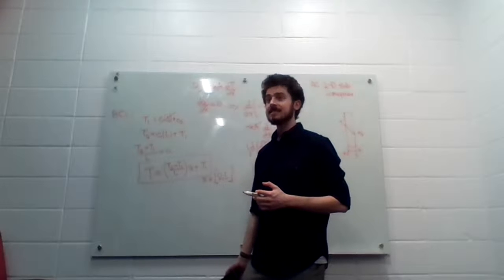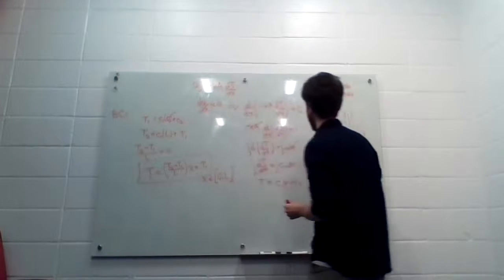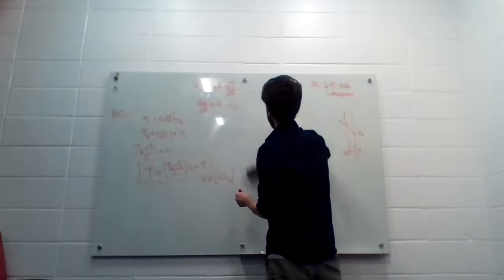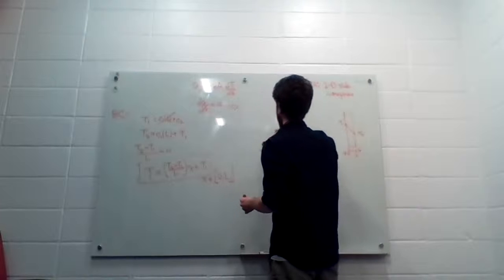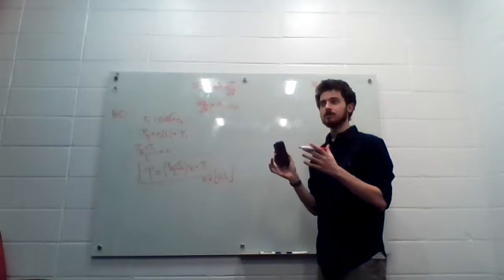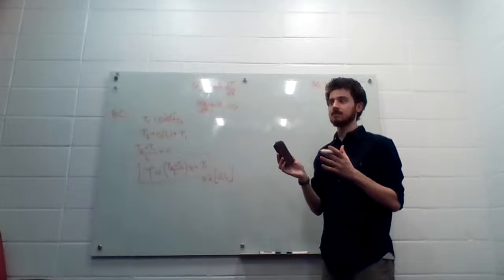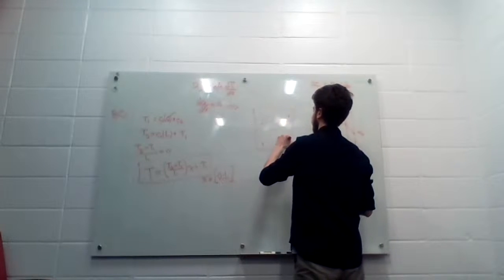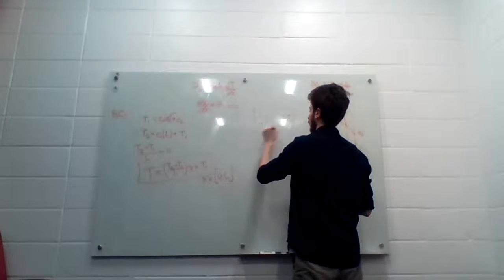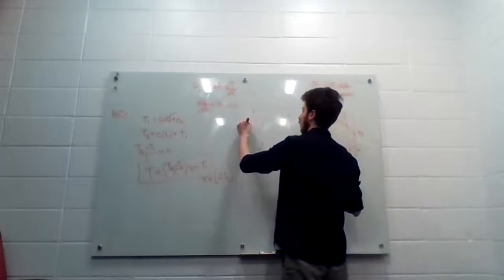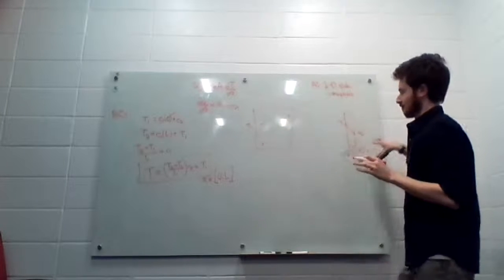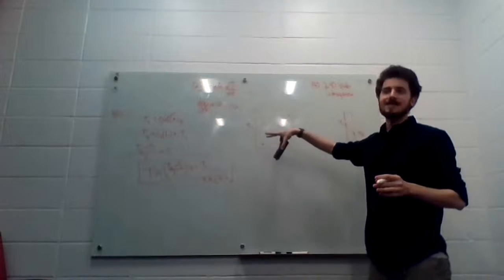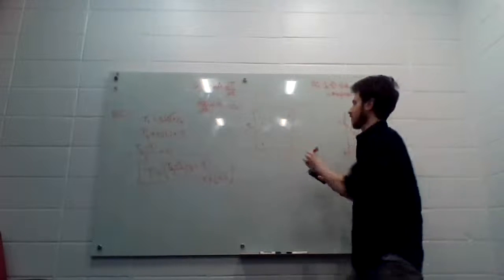When you're talking about gases, it makes sense that when you have a higher density of particles, you get higher thermal conductivities. Because if you're in kind of a vacuum and there's just a few particles, it's very hard for energy to transfer from your one wall. Sorry, I'm kind of cheating the problem, but this is a different problem where you've got a gas between two walls at different temperatures.